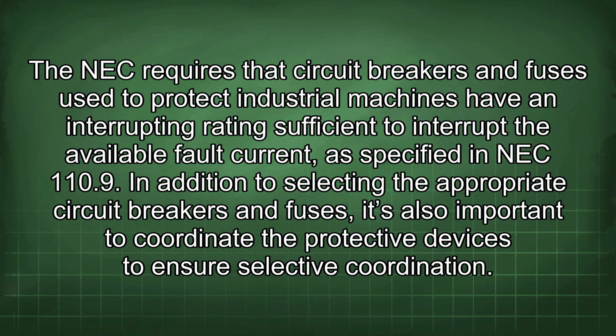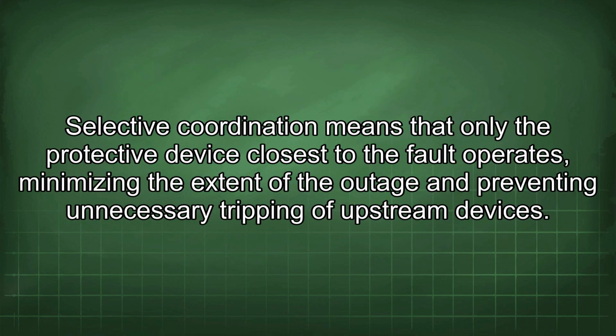In addition to selecting the appropriate circuit breakers and fuses, it's also important to coordinate the protective devices to ensure selective coordination. Selective coordination means that only the protective device closest to the fault operates, minimizing the extent of the outage and preventing unnecessary tripping of upstream devices.